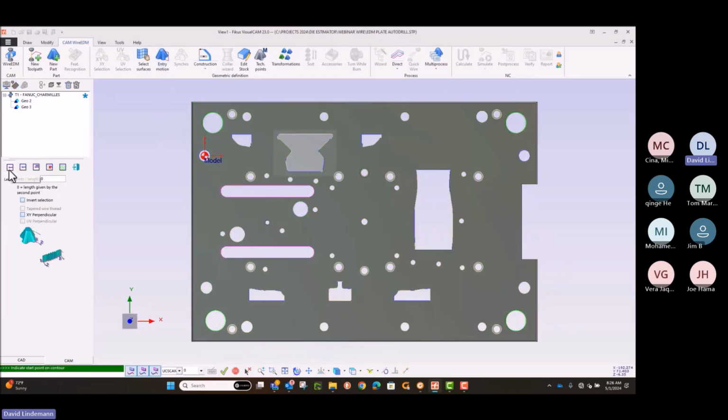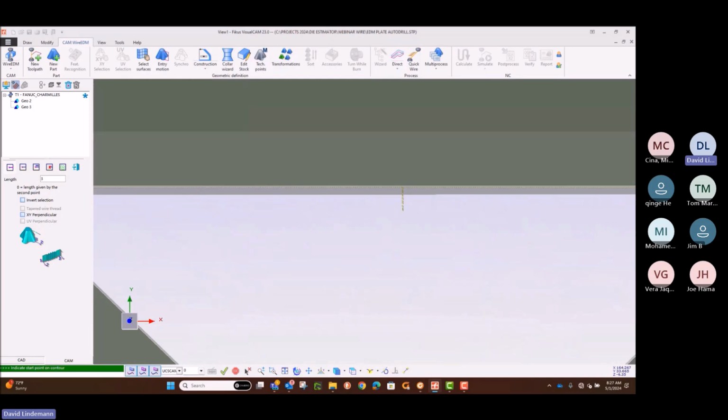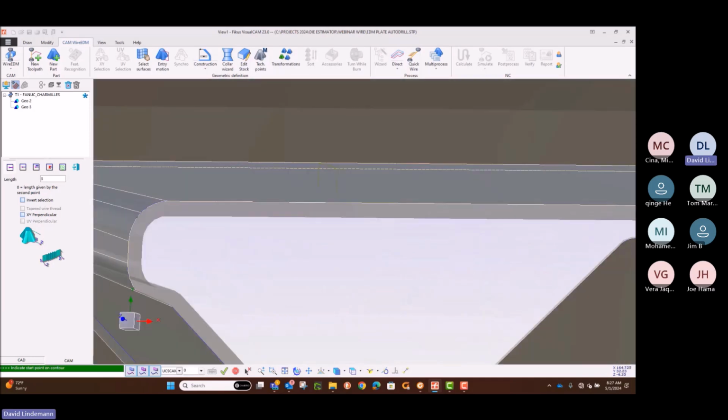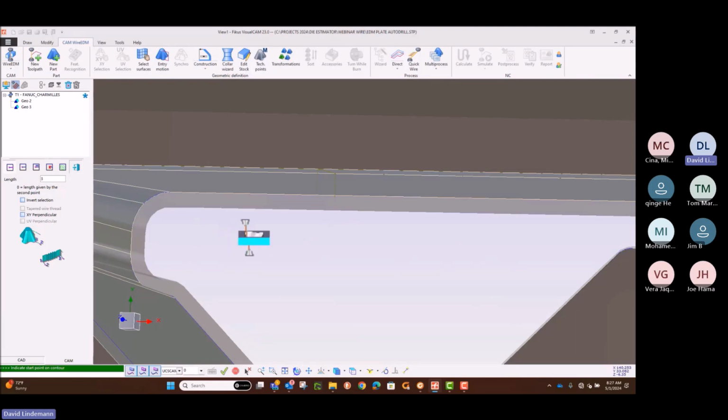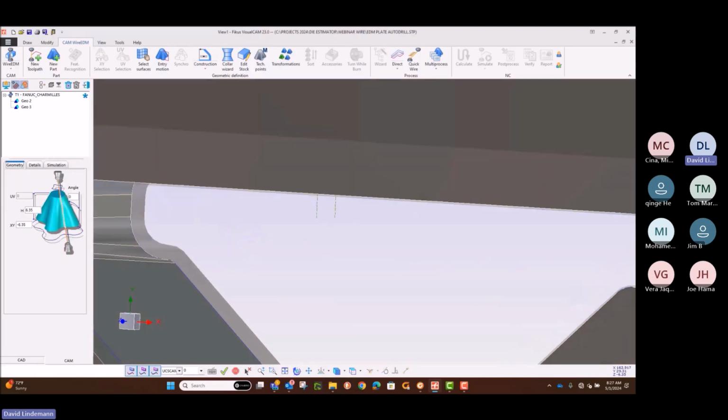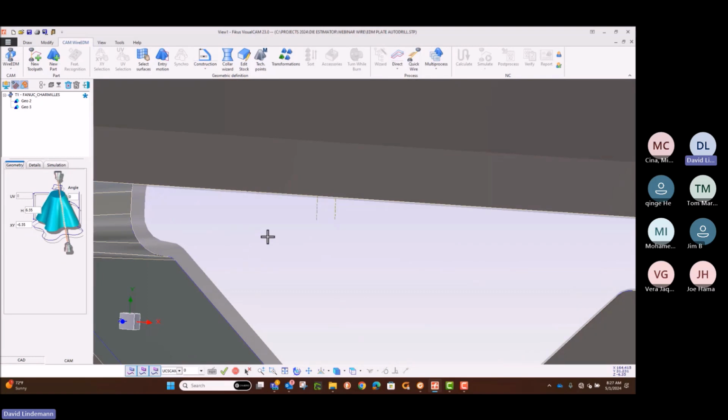We describe how we want it to come in with our entry of our wire. So I might say I want to come off 3 mil off of the length of the part right here, or right here off this midpoint of the line. That's my entry of the wire, so that's where my 1/8 or 3/16 drill hole would go to have that wire start. That can also be designed as part of what we're doing with our die design package. All right, so you can see the entry. Everything is almost set up. We want to be able to do like a variable conic with this as well.